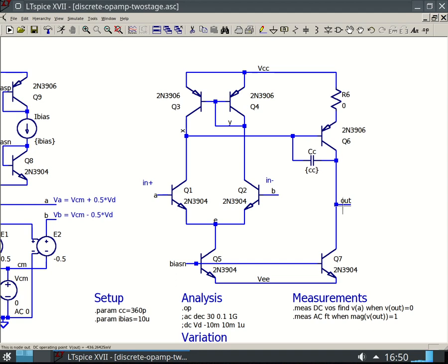If, this is an if because it's not necessary for this situation, if we had a DC operating point solution that gave us one of these transistors in saturation mode, or cutoff mode, but it would be saturation mode in this case, any simulations that we do after this, especially the AC simulations, would be bogus. And when I say bogus, I mean bogus. Not valid. Not even worthy of plotting them or even doing the analysis. I know it takes like a second to run the analysis, but it's still a waste of your time.